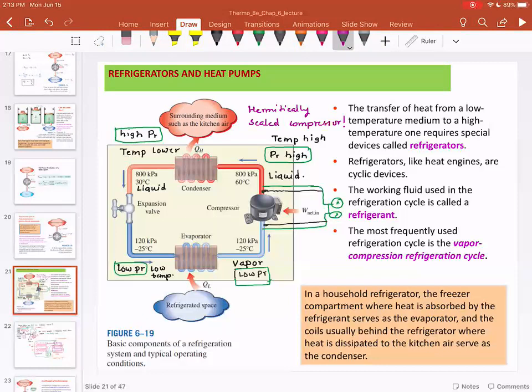Which means if there is a teeny tiny opening, say if you have a crack in the condenser or a crack in the evaporator, believe you me, all that refrigerant will get out of this system in no time. That's why you use special O-rings, those are of green color, and special lubricants and special sealants to seal this closed system.